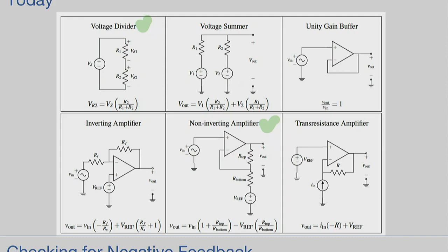So the U in and U out for an operational amplifier, are they just references, or does the op amp get power from U plus and U minus, or does it get power from VDD and VSS? Oh, very good question. Where does the power come from? Sometimes you can connect one of the U plus or U minus for power, and the VDD and VSS also could be used. Typically, they are the same, VDD and VSS, so you can give the same voltage there.